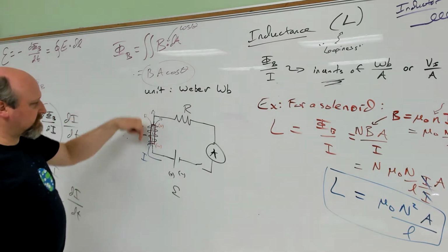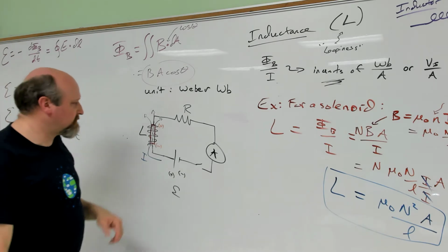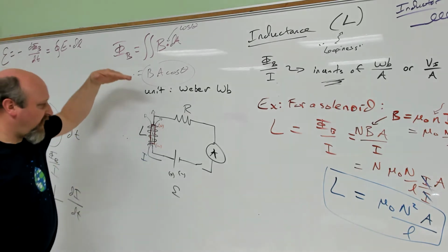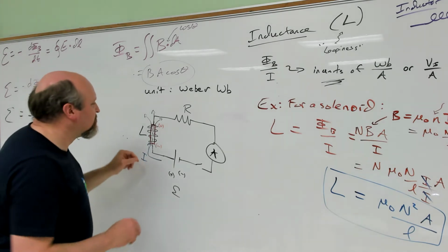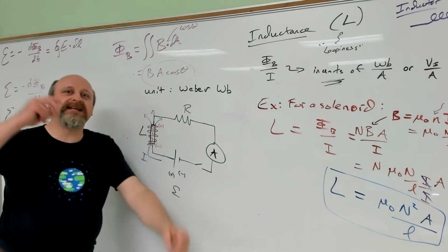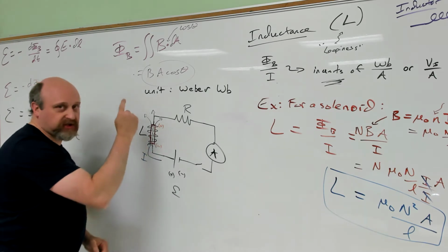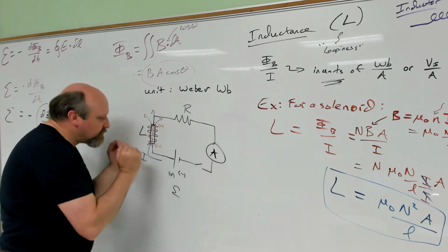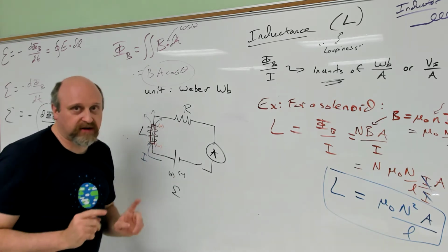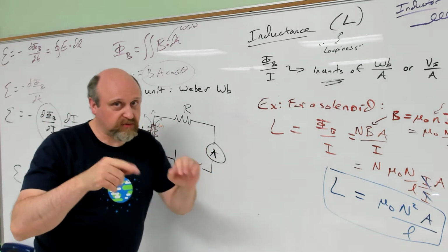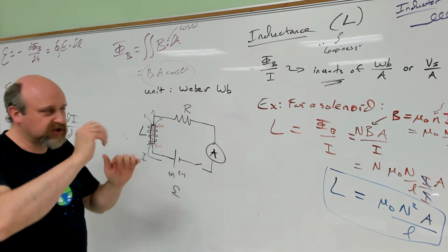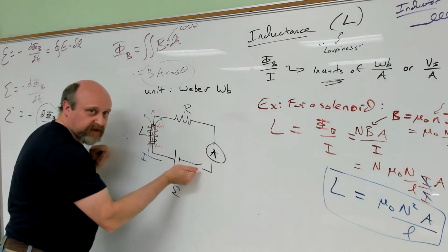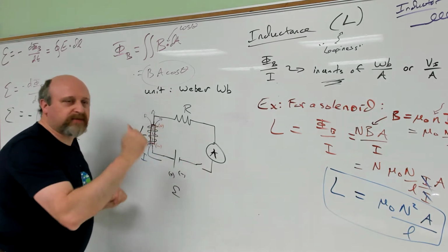How big of a voltage will this make? The answer is, it will push hard enough, and this is the way to think about it, so that you cannot have an instantaneous change in current. It forces the current to build up from where it started. We'll do it with other cases where it's already flowing some and then we make a change. In this case we're starting with zero current and then I click the switch. It doesn't just jump up to be the maximum current.